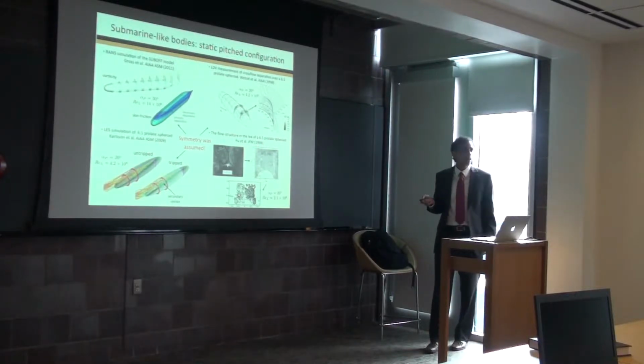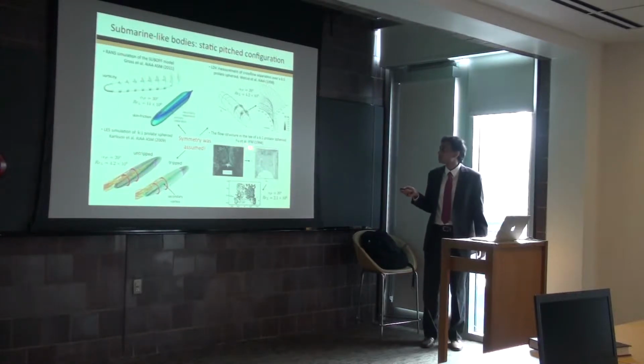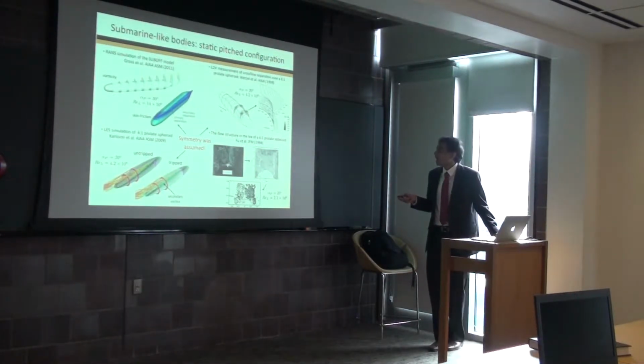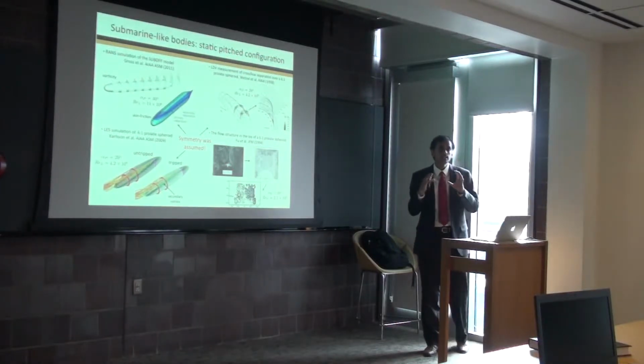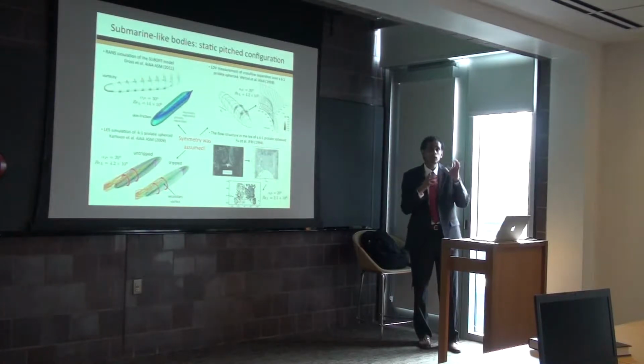Fu et al., it's interesting to note, Matt Fu, who now works for Marcus Halpmark, that's his father who did this work, so this is an experimental fluid mechanics family here. And they noticed that they didn't assume symmetry. So here, this is an early particle image velocimetry work where they look at the instantaneous flow structure, and they in fact find that instantaneously the wake on a body that's nominally symmetric can actually be asymmetric.